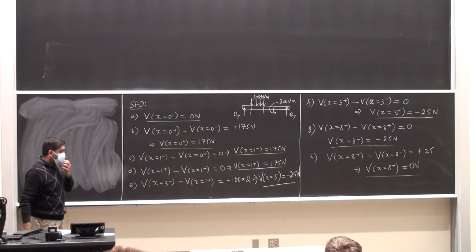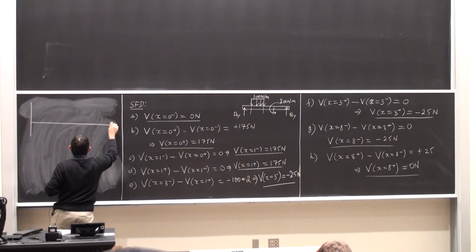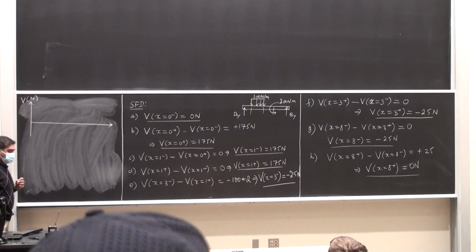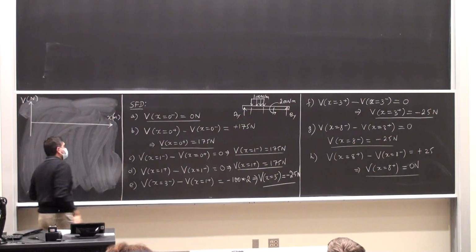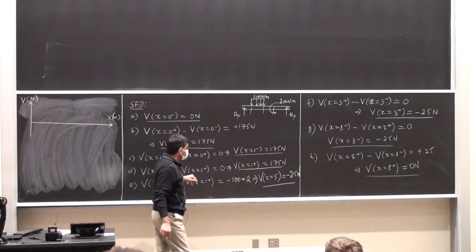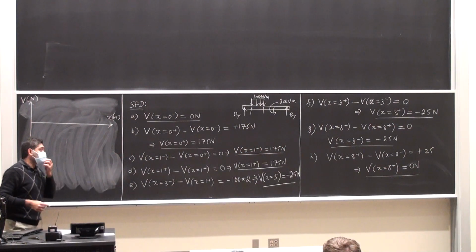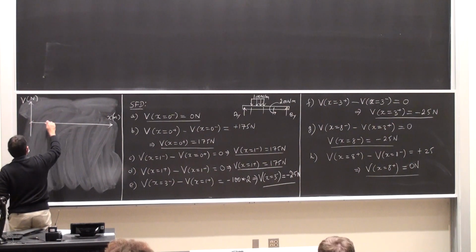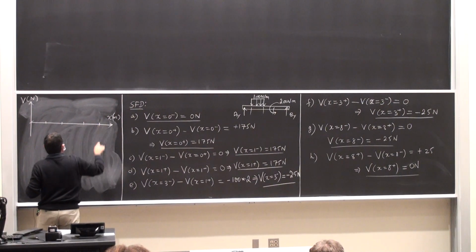You know the distances. So I'm first going to mark the distances. My shear force in newtons, x in meters. What are my stop points? 0, 1, 3, and 8. In between I also mark this 6 meters because I know that there is something going on which will be useful for the bending moment diagram. So 0, then 1, then 3, 6, and 8.